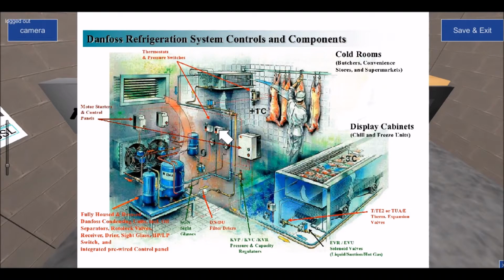That is set up on the electrical, so the control of this is that it supplies the electrical power, 220 volt in this case, to the compressor. Once the refrigerant empties out of the evaporator and the back pressure drops to 0, this pressure switch contact will open, thereby killing the power to the compressor, and the compressor cycles off. There's a built-in differential inside here.